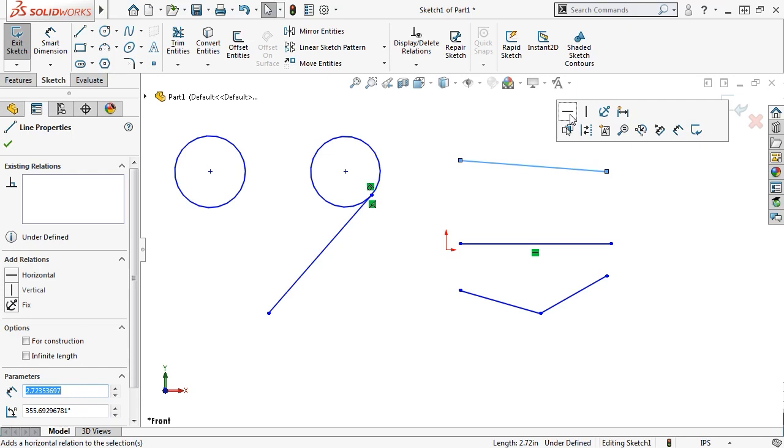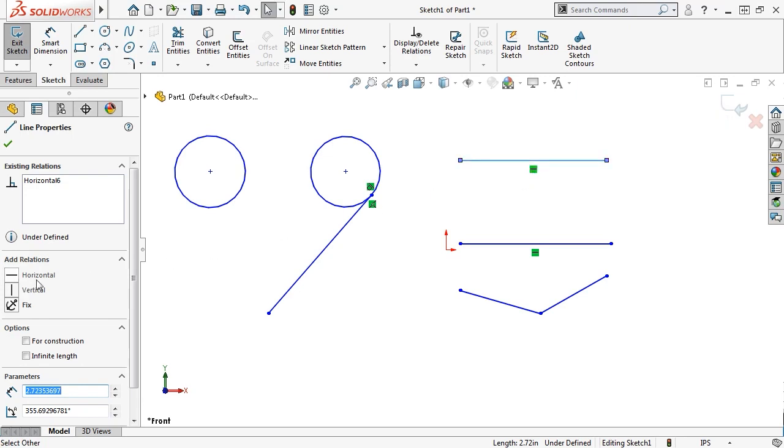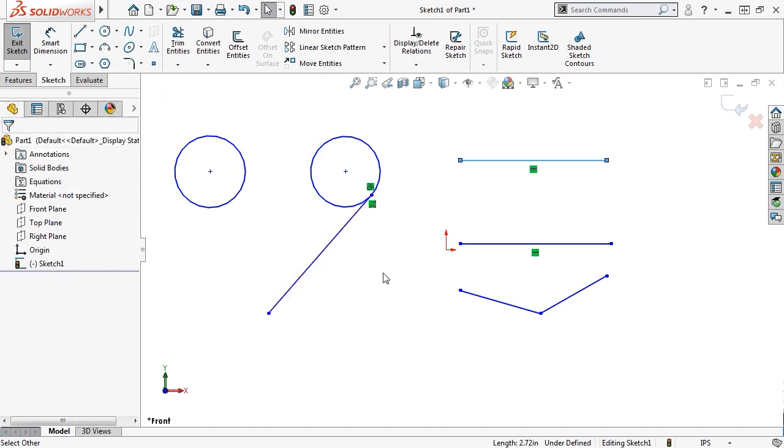box around it. If you are new to SolidWorks and geometric relations, I would suggest using the Property Manager. This way, you can see the name of the relation next to each icon. Once you get more familiar with geometric relations, you might find it faster to use the Context toolbar instead. The options you see in both the Property Manager and the Context toolbar depend on the geometry you select.